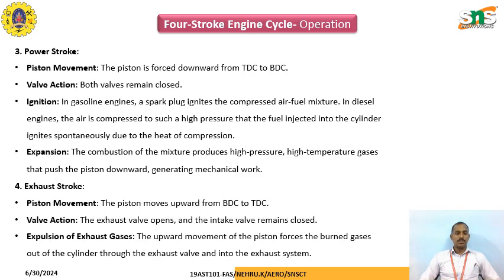The third one is power stroke. The piston is forced downward from the top dead center to the bottom dead center. Both valves remain closed. In a gasoline engine, the spark plug ignites the compressed air-fuel mixture. In a diesel engine, the air is compressed to such high pressure that the injected fuel ignites spontaneously due to the heat. Expansion: combustion of the mixture produces high pressure, high temperature gases that push the piston downwards, generating mechanical work. Final stroke, exhaust stroke.